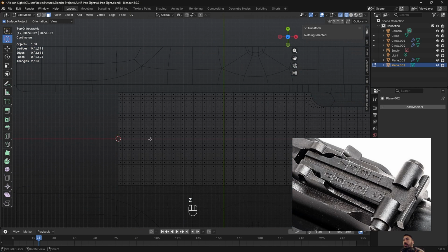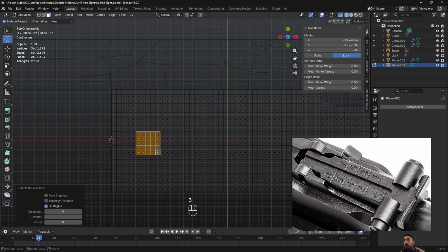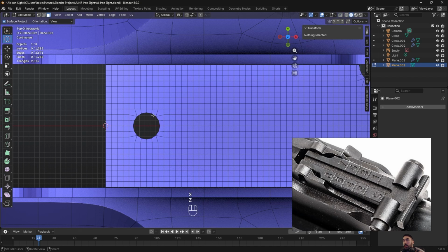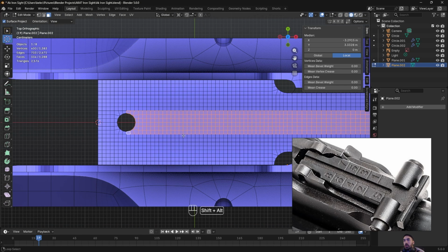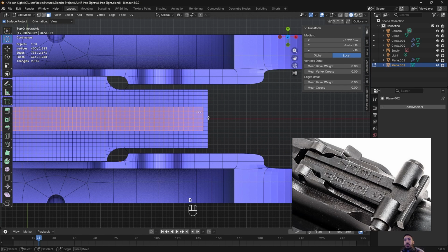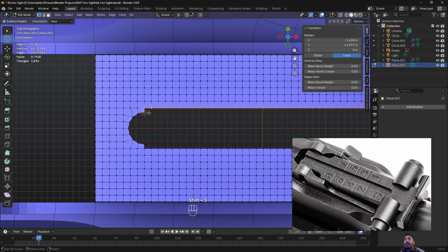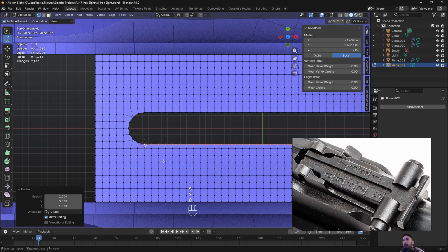Over here on the front, we take something like a 4x4 surface, because that goes straight through the middle. W loop tool circle, we delete that circle, and then we also delete everything on the right of that circle like this. So this entire area back here we're going to get rid of. So select those faces, get rid of them, place the cursor up here, select this edge segment, extrude, right click, scale to 0 on the Y. Same thing down here at the bottom.